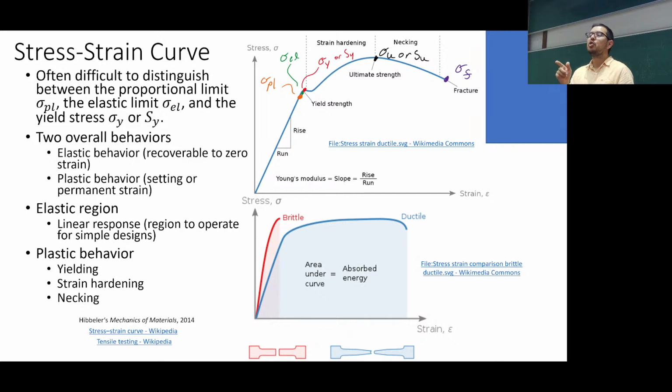So sometimes the goal is just to enhance the strength of the material or the structure at its surface. And steel cooperates synergistically with this effort. You can quench a steel with temperature. You heat it up, let it stay for a while at a high temperature, then put it in water, quench it real quickly, and it becomes very hard. Because there's a thermal gradient as the quenching occurs, the hardest, strongest portions are going to be at the outer edge that got cooled the quickest.